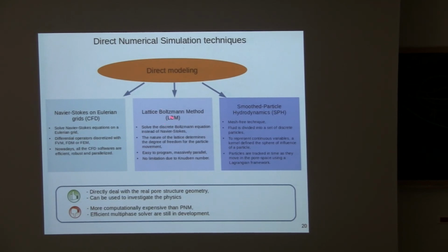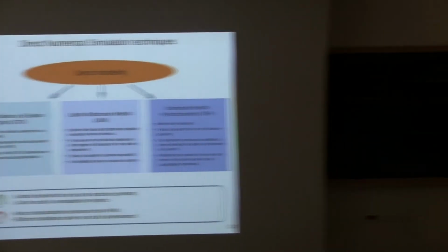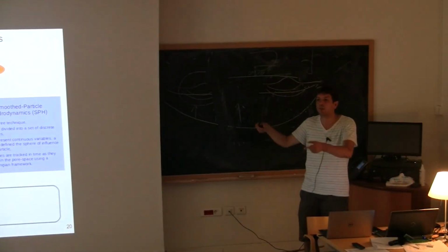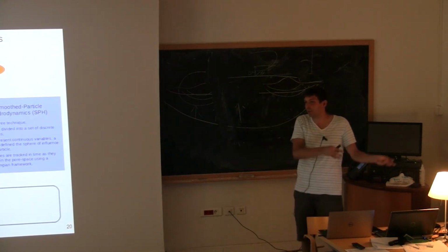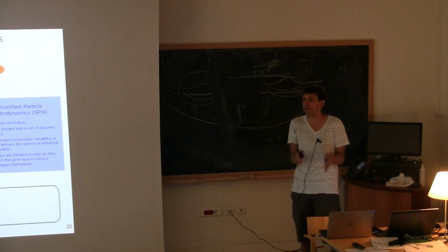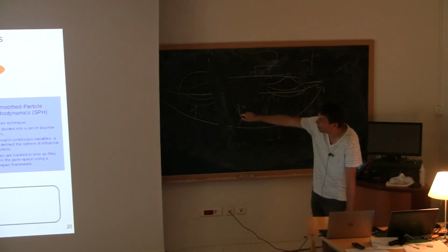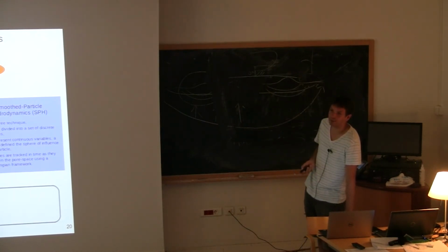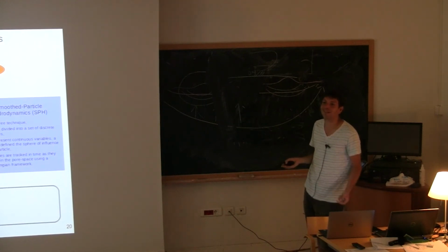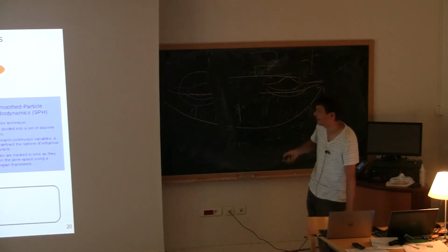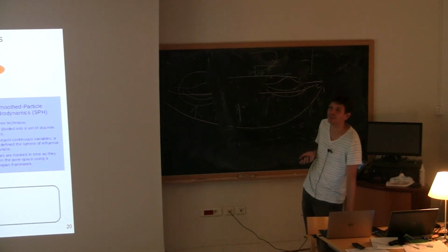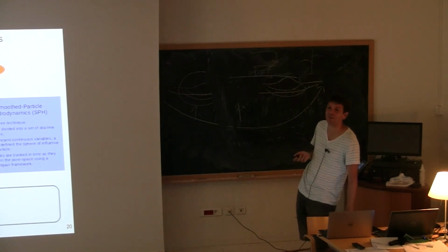When you work with all these approaches we call CFD, they are based on a mathematical construction where you start with mass and momentum balance and you obtain the Navier-Stokes equation, we discretize the equation, we solve the equation. So we know all the construction and we know it works well for fluid, liquid, and gas. When you work with the Lattice Boltzmann method, you don't work with the Navier-Stokes equation, you work with the Boltzmann equation of statistics, and this equation was formulated initially only for gas. So there is no proof actually that it converges to the Navier-Stokes equation for liquid.